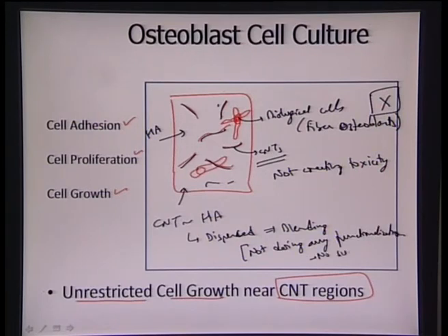No surface treatment has been done on the CNT surface. So with no functionalization and no surface treatment of CNT, they are still getting dispersed into the hydroxyapatite matrix without any hindrance. They are getting distributed uniformly on the hydroxyapatite surface without any functionalization. That is the reason it appears that they have some sort of a chemical affinity with the hydroxyapatite surface, and that is why they are distributed so uniformly even after plasma spraying, and they are able to enhance the fracture toughness by approximately 2 times.